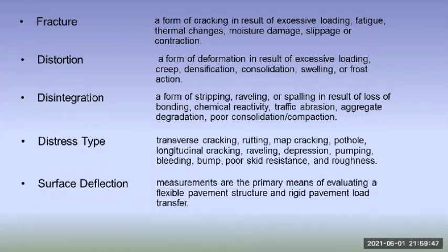Disintegration, a form of stripping, raveling, or spalling as a result of loss of bonding, chemical reactivity, traffic abrasion, aggregate degradation, or poor consolidation or compaction. Next is the distress type.